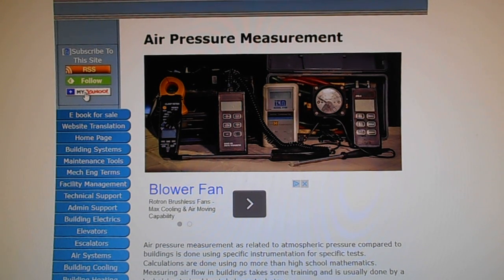When the supply and return air volumes are correct, the technician is required to adjust individual exhaust air grill balance dampers to increase or decrease exhaust air flow to individual areas or offices. At the end of the air pressure measurement and air balance, a report must be compiled detailing all fan and diffuser design and actual balance conditions.